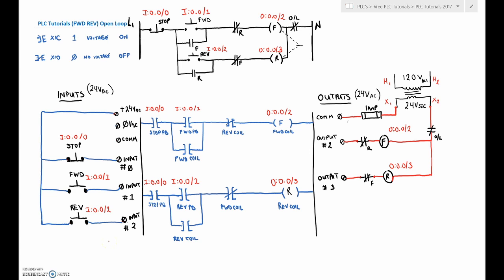so that's everything. The last thing we need to do is just address each of these guys, our electrical interlocks and our holding contacts, and they're going to be addressed with these same output bits that we just looked at for the forward and the reverse. Okay, so let's start off with the forward coil. This holding contact right here is just going to say, all right, when this guy turns on, then examine that it's on. So we're just going to look at that bit of information in the PLC, and we'll address that guy as our output.